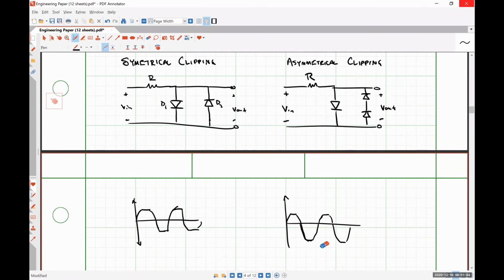You can also accomplish asymmetrical clipping just by using two different types of diodes. Some modern effects pedal makers like Brian Wampler have started using different colored LEDs inside their effects units to do asymmetrical clipping, because different colored LEDs, and I mean truly different, not an LED with a green plastic cap on it to make it give green light, but a real LED that emits green light versus an LED that emits blue light, have different characteristics, and so they'll give you asymmetrical clipping.